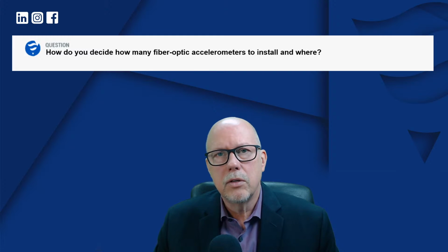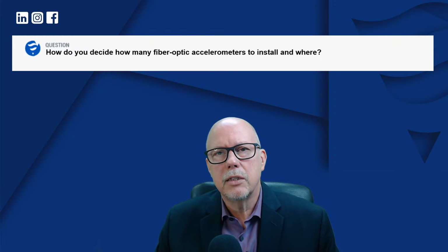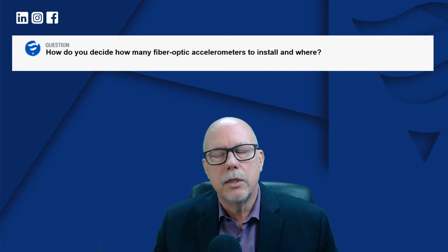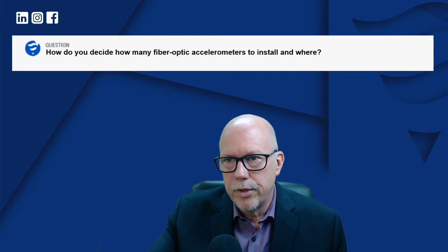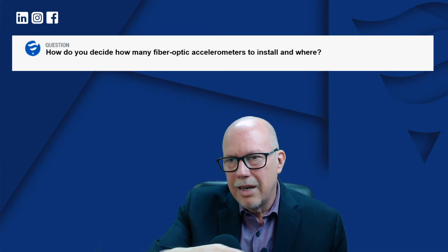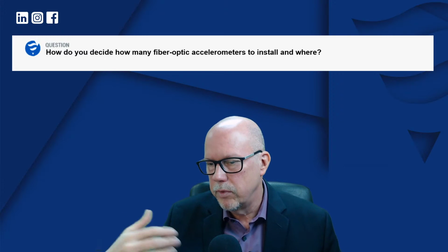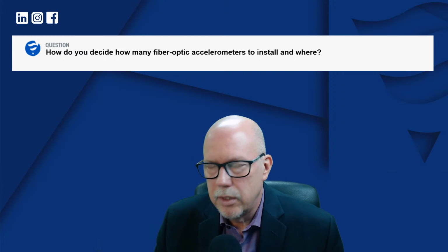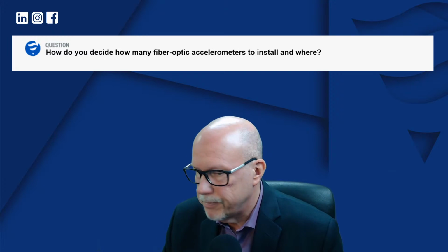And in some cases, there's no evidence of any problems. The utility just wants to be proactive and wants to protect the asset, and they decide to invest in some end winding vibration monitoring. And in those cases, we have an approach where we simply put them symmetrically all the way around in both ends. I know some people think that on the drive-in, since the end windings are much shorter and there's no phase leads, there's a lot less material, that there's no issues there. But we've seen as many failures on the drive-in as on the non-drive-in. So we install sensors on both ends, and then we train the people to be able to analyze the results and get a better idea of the health of their unit.